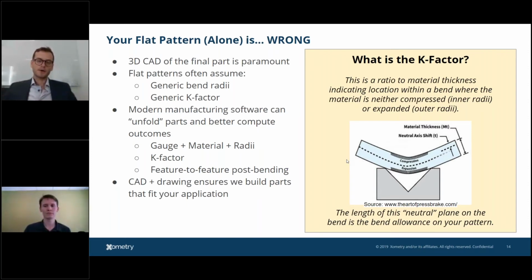If you're doing 90-degree bends, that top die that you saw in the other picture is 88 degrees. So most likely, that's to account for spring back. So you're most likely doing bottom bending. So if you look at the table, pick the bottom bending number. That's good to know. I didn't. I just learned that. Awesome.